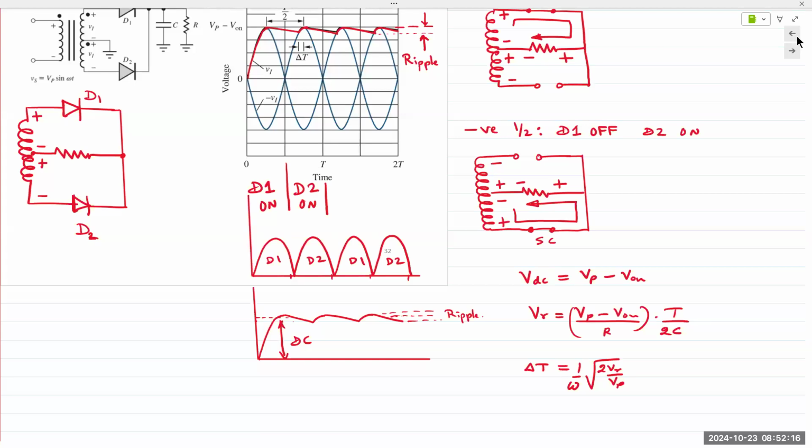And so the Zener diode is a very popular voltage regulator. You simply connect a Zener diode at the output, and the capacitor output, which might have some ripples, would be eliminated. All we have to ensure is that the input voltage is large enough to actually turn the Zener diode on. And that we'll study right after this one.